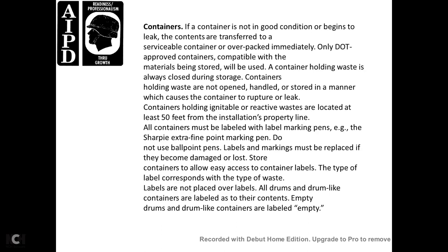Containers holding ignitable and reactive waste must be located at least 50 feet away from the installation property line. All containers must be labeled using marking pens, such as a Sharpie extra fine point marking pen. Do not use ballpoint pens. Labels and markings must be replaced if damaged or lost.